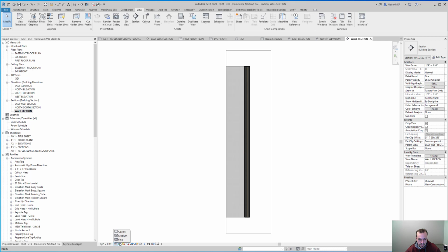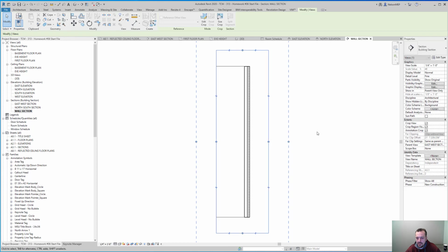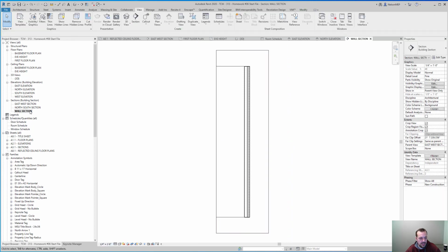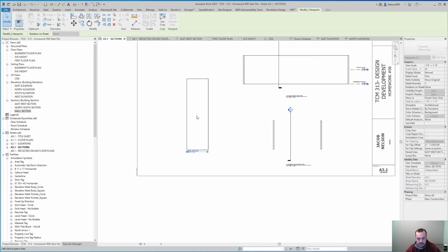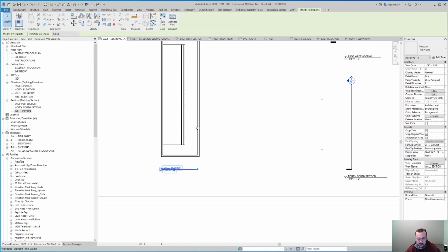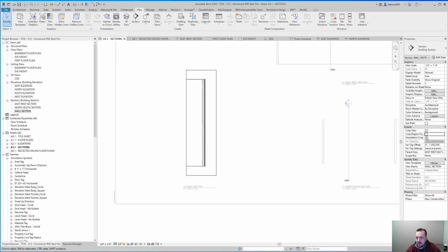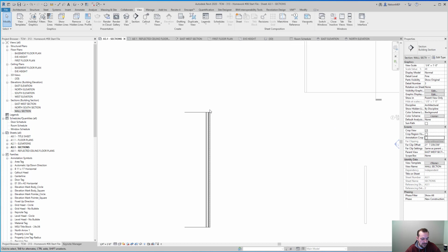Probably won't do realistic view. Do it. There we go. So now we can add that text as we need to our wall section. It should be at a 1/4 inch scale. I can add that wall section to my section views over here. And I want everybody to be sure they label some text with that. Kind of like we did on the previous, and I can get rid of my annotation and crop view and really clean that up. And you also should have a little roof that's coming up here that you can annotate and look at.